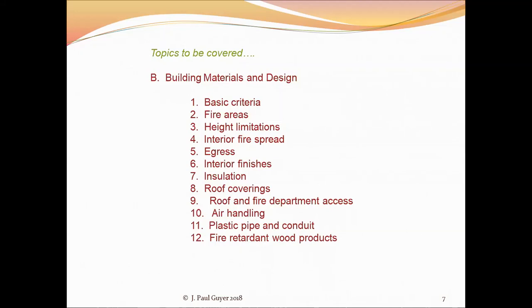And then the pumper truck is down on the ground and the pump is turned on, and that increases the pressure in the risers so that the water will go all the way to the top of the building. Because the pressure for typical municipal water systems will only get the water up to around the 10th floor in a multi-story building. Above that, you need to increase the pressure using a pumper truck.